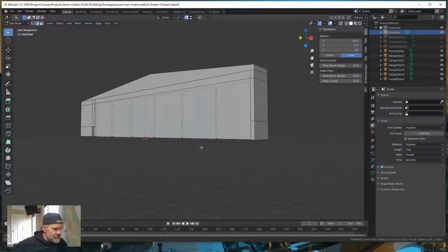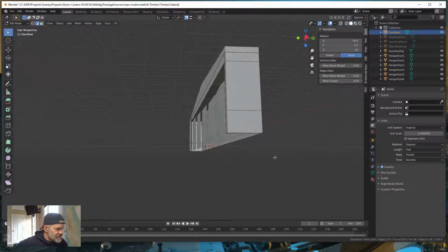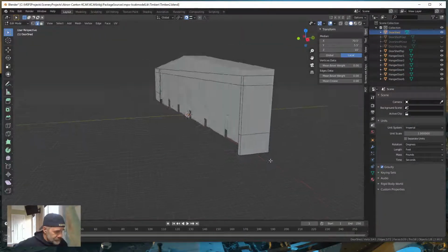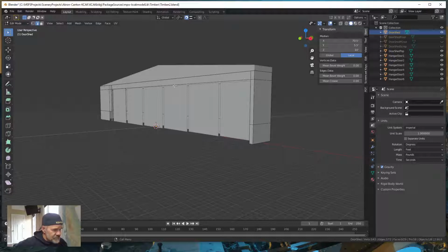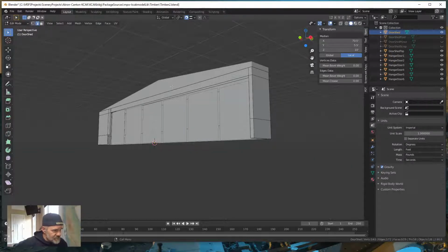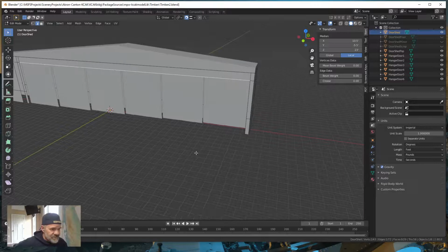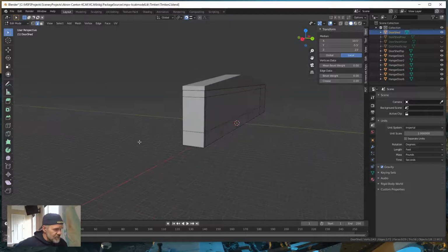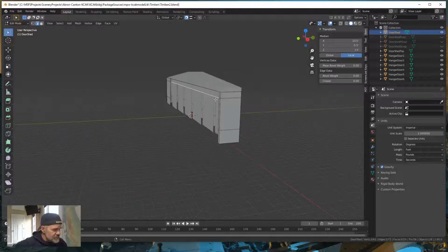We're going to do the same thing with our ceiling. We're going to bring that ceiling all the way across. Okay, same principle. So select the edge that you want. Make sure you're on edge select. Select that edge, which is the top of our door, right? And we are going to extrude that with our snap to edge in the Y direction to snap on this edge right here. So make sure your snap edge is on. Make sure you have your edge selected.